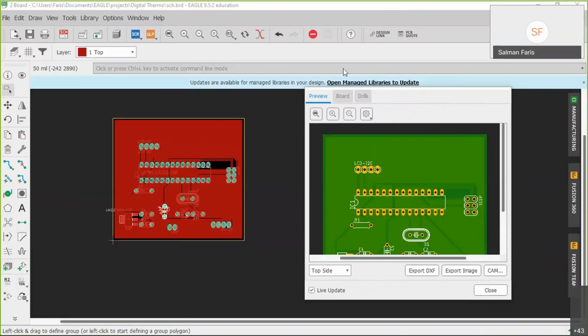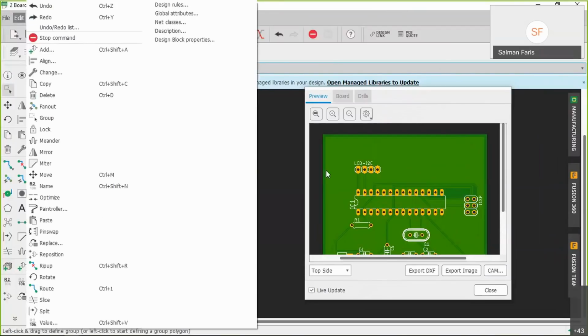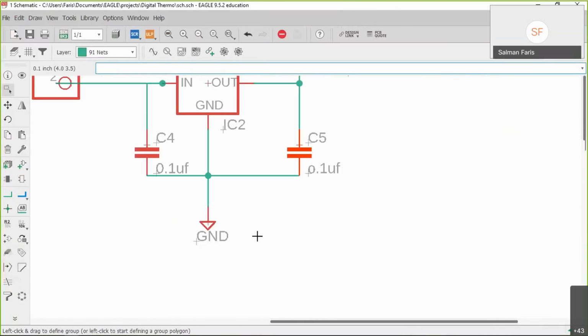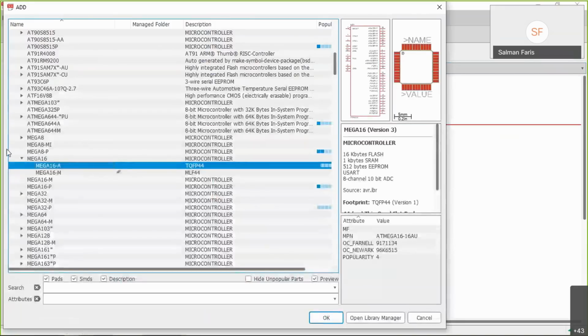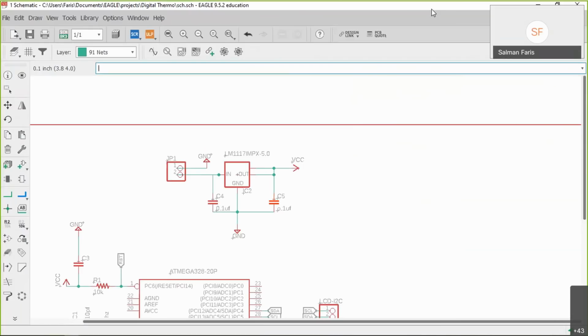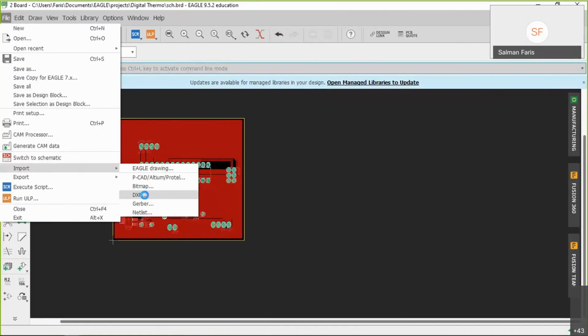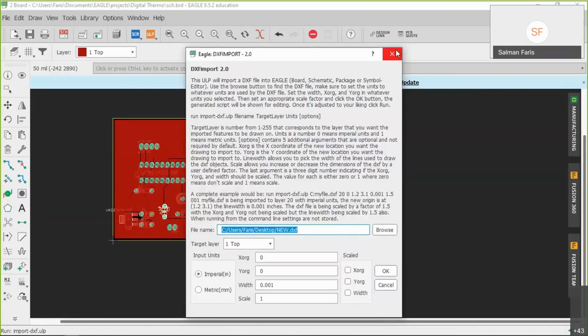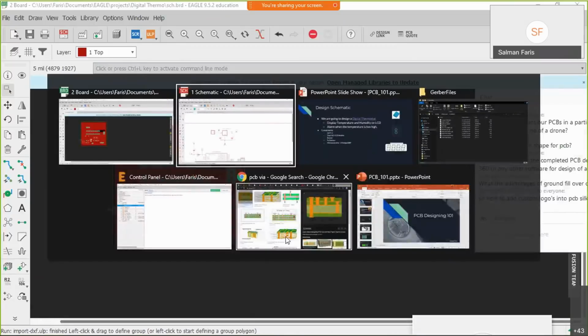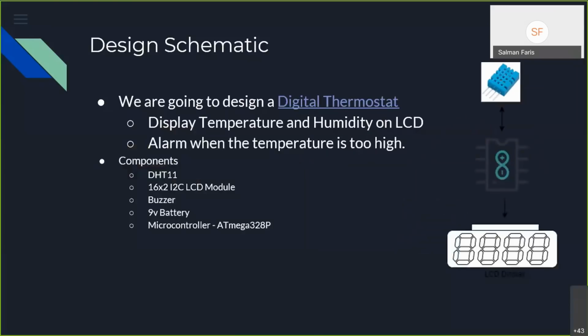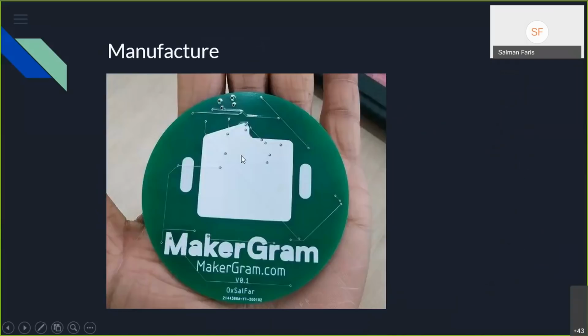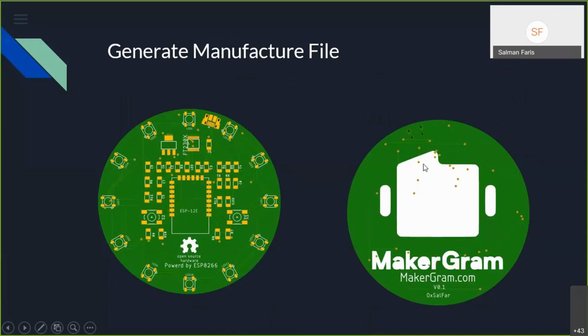That's a good question. One thing we can do, as people normally do, I'll show you. For the PCB silkscreen, you can import DXF files here. You need to design the DXF, convert it, and import the DXF into the PCB design. So you can make designs like this one, exported from the DXF.